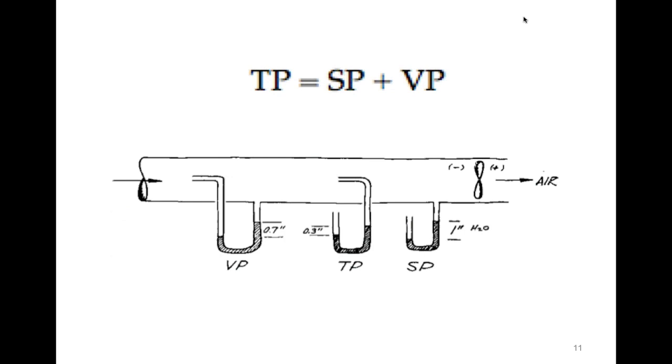So what will happen is it'll pull that water up until the difference in the heights of the column of that water, that weight of water that's different between one side and the other, is equivalent to the suction on that side of the duct. And we call that inches of water of vacuum or of pressure.